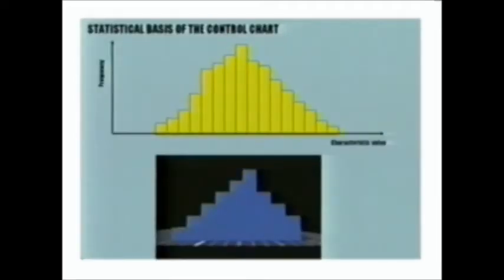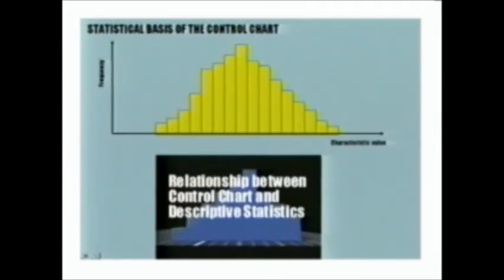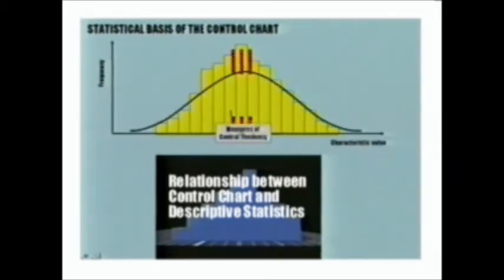The power of a control chart stems from the fact that it provides a simple way to display the pattern and the source of process variability. In statistical terms, a process population should be described using what we call measures of central tendency. These are measures around the center, and measures of variability or dispersion.